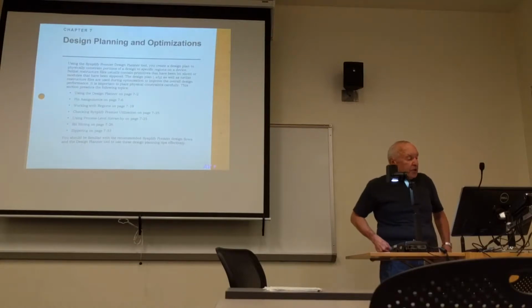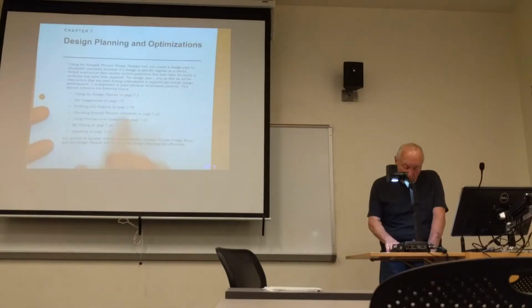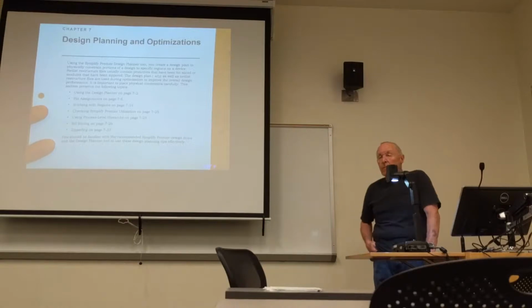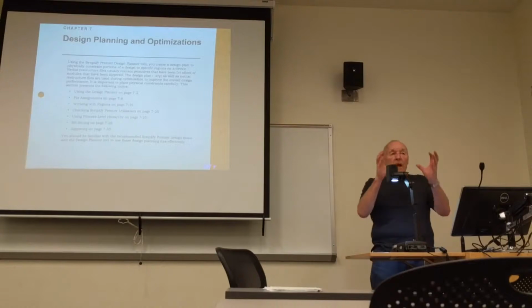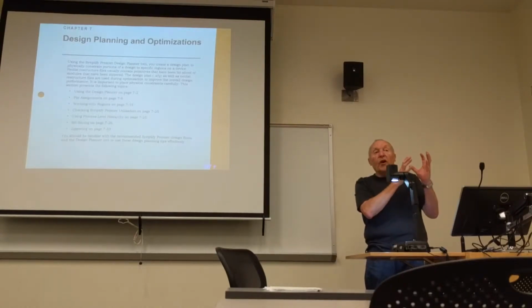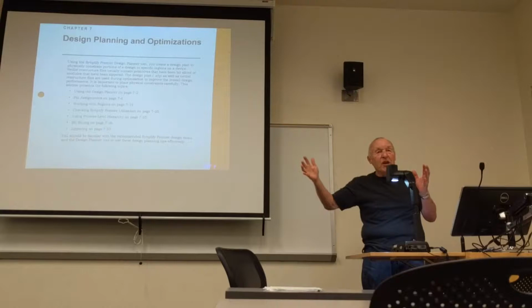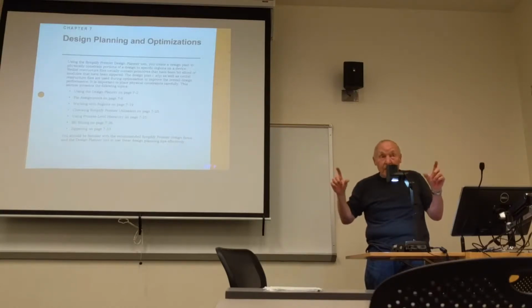Design planning and optimization. This uses a tool called Design Planner. This talks about pin assignments. To show you the effect of pin assignments, and you'll see an example later on when we talk about timing constraints, if I have my logic on one side of the chip, and the output of that, which goes to output pins, are on pins assigned on the opposite side of the chip, you have rather long traces. That's not a good placement.